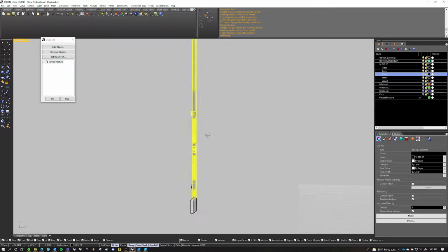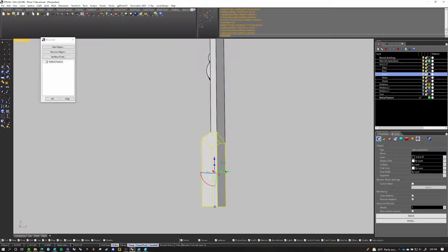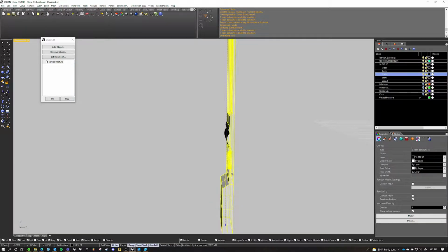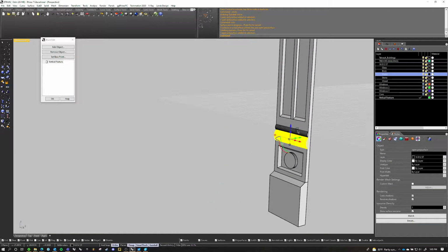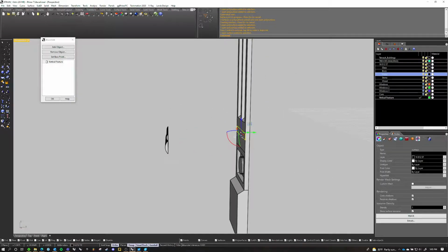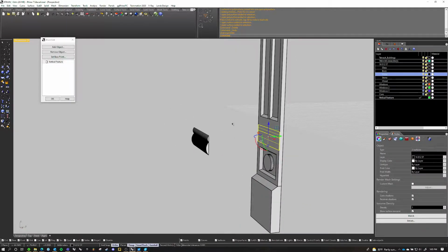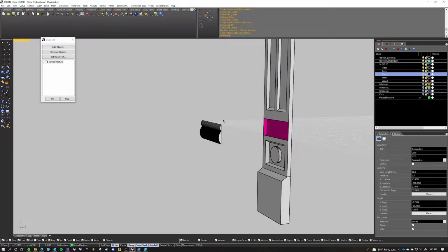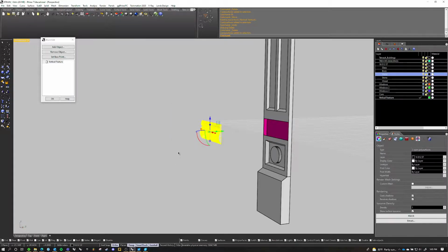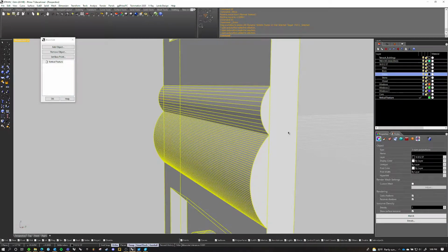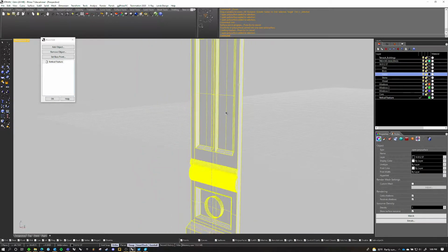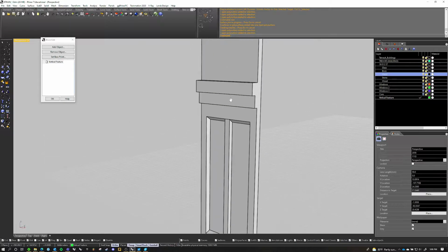This is still an open poly surface for some reason, so I'm going to move this, see if it's, yeah, it's not joined. So if I just join these together, that'll probably help. Behind this is probably messed up. Yeah, those aren't joined, so you can see. So I'm going to move these back and just join that. You can join surfaces, not objects, not solid objects. Let me see.